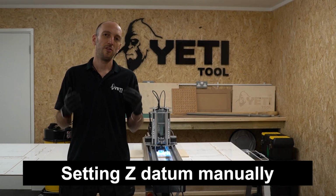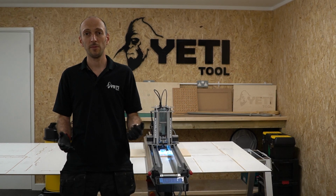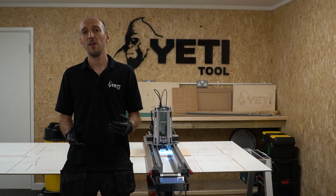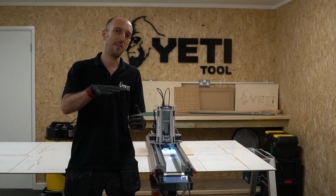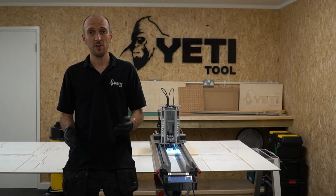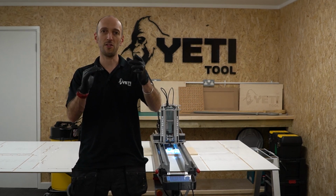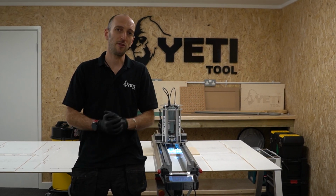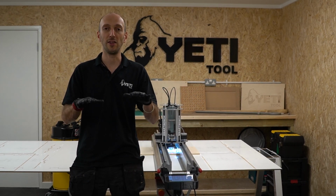The alternative to using the Z height Pro plate is to set it manually. And you might need to do this if you're in an application where you don't have much of a contact patch for your Pro plate to sit. In this instance, you would drive the tooltip down manually, and when you can see that it's at the right height, you press the set button and SmartBench will position its working datum at that height.